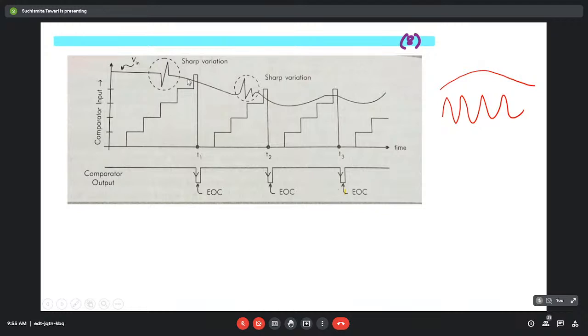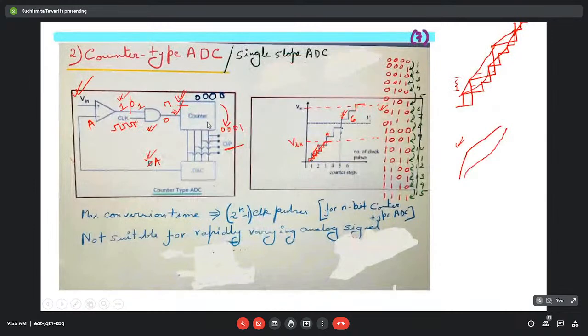And once the signal has been detected, that is, once the reference voltage crosses the input voltage, it won't get cleared again. It won't drop down to zero again. Instead, it will now track this entire signal. So that bit of modification needs to be done in this present circuit.